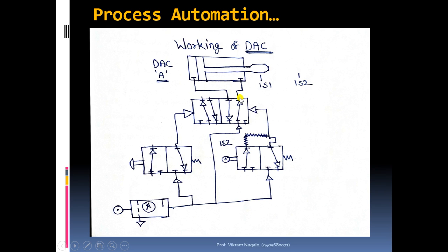In the case of the right side block, it goes to the second port; here it will be given to the fourth port. And this second port of the valve will transfer the air to the input side, meaning the air which was going inside the cylinder from the right hand side port will be given to the atmosphere through port number 3.